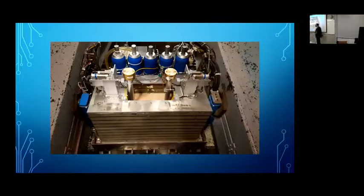So this thing looks, when you put it on a centrifuge, something like this. You can see these actuators are quite small. Remember, at the beginning, I said to you, in the centrifuge, the big advantage is we can apply quite a large prototype force by using fairly small actuators. This is all the actuator we have in the centrifuge. Whereas if I want to apply the same load on a prototype pile, I can't even do it. I need such big actuators.